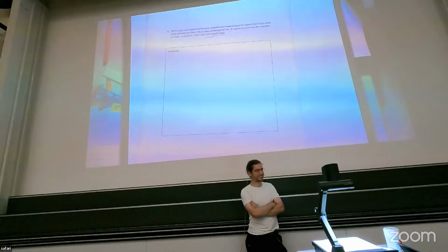Right? Now the question is, what selects it? And you say, hey, there is an additional bit here. This additional bit is actually an address bit. So 8 of the address bits come from here, 1 of them goes here. Now you can say, is it the least significant bit or the most significant bit? Or is it a bit in between? What do you say? Who says most significant? Who says least significant? Nobody says least significant. Oh, come on. Who says it doesn't matter? Yeah, it doesn't matter actually.